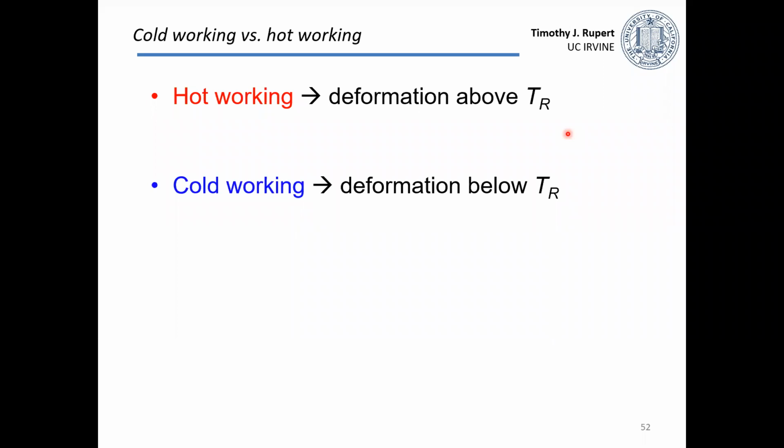Sometimes they put that sword into a hot furnace and it's glowing bright orange, and then they're hitting it. When they're doing that, they're hot working their material. They're trying to change the shape. Then when it cools down, it's no longer glowing red. If they keep hitting it, at that point, they're cold working their material. They're trying to deform it so they can change its properties.